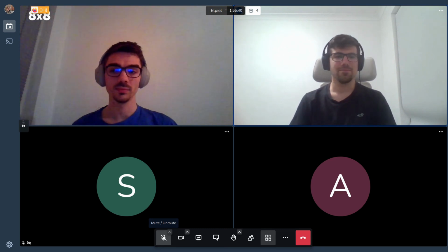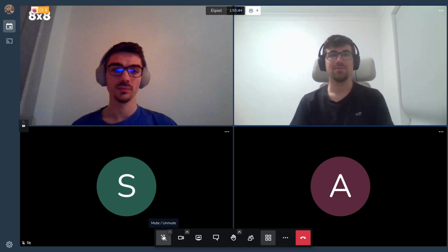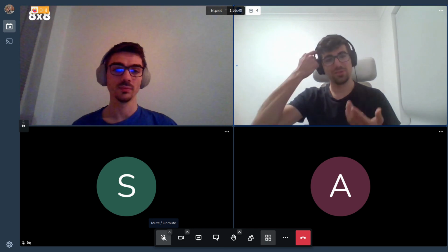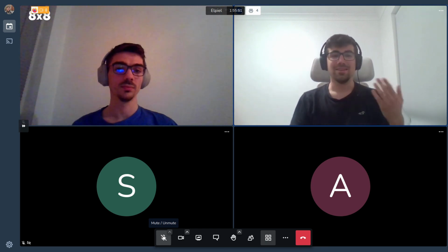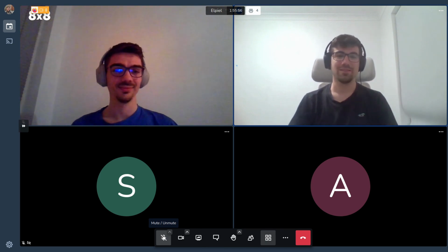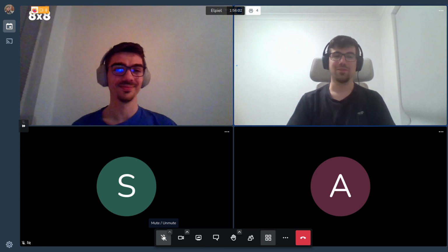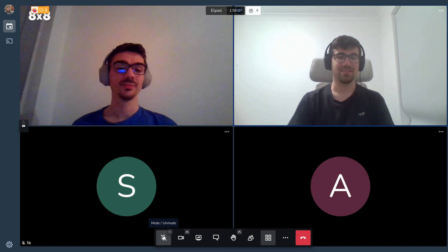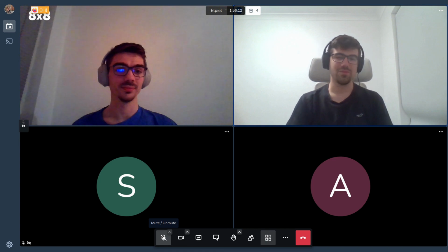Sometimes the EPS or the OBC doesn't come up when it tries to start in sunlight, because the EPS gets some weird signal through the solar cells, and that prevents the boot. It's very obscure, and we don't really know why that is happening. But we observed that a couple of times testing on the ground, and we fear that could be something that could have happened.